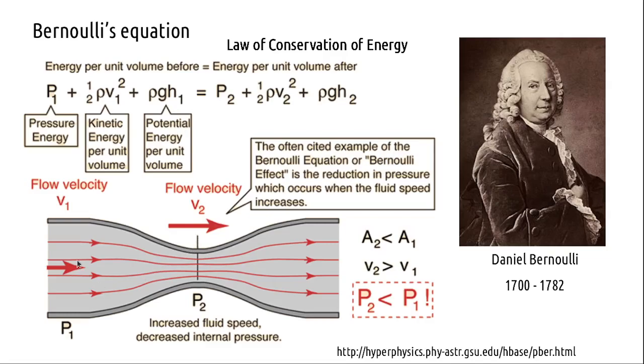So that explains the flow across constrictions. Okay, so there is the flow along a constriction. When the fluid flows, there is an increase in velocity. That means the kinetic energy increases. Consequently, there is a decrease in the static pressure. Okay, height is the same, so h1 equals h2. So there is a transformation from static energy to kinetic energy.